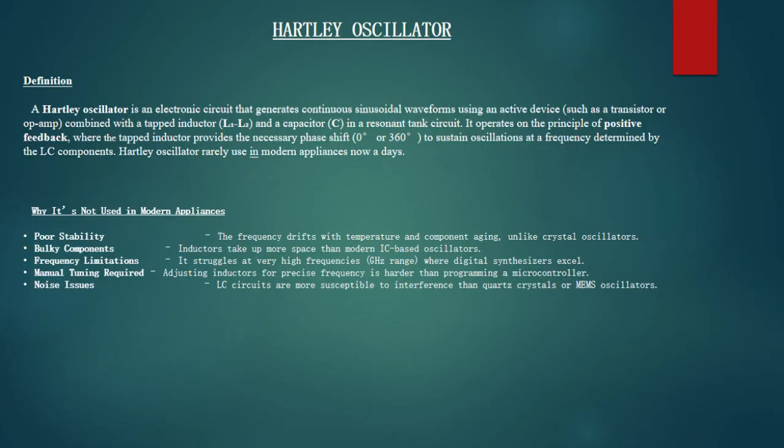The third reason is frequency limitation. It struggles in the high frequency gigahertz range, where digital synthesizers excel. The fourth reason is manual tuning required. Adjusting inductors for a precise frequency is harder than programming a microcontroller. The last reason is noise issues. LC circuits are more susceptible to interference than quartz.